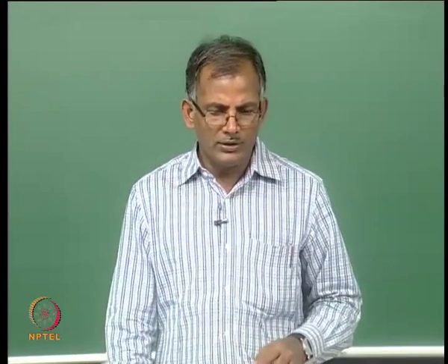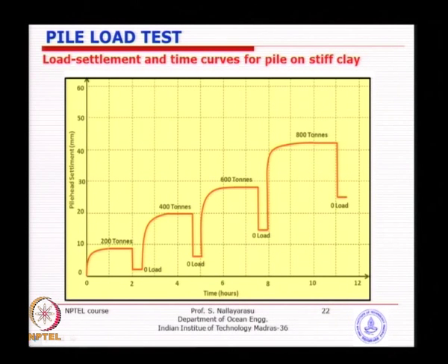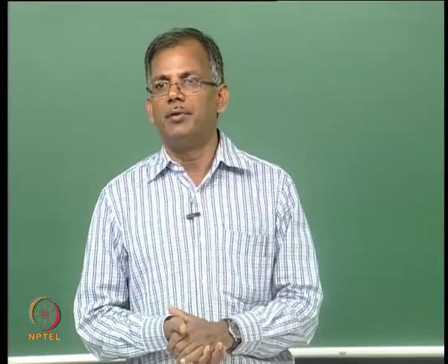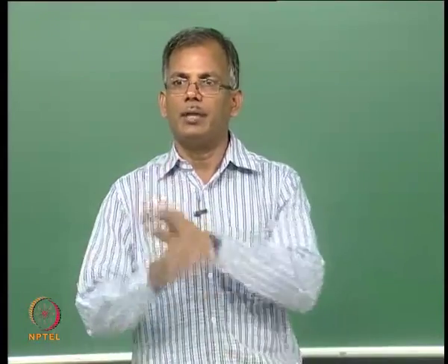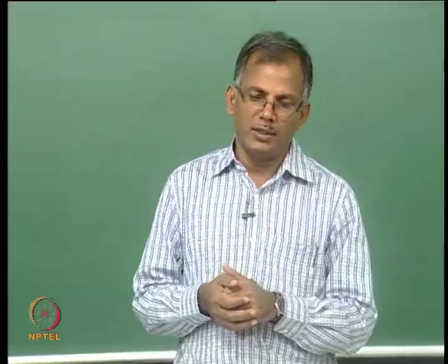So, the maintained load test is quite simple, and we will see the procedure later on, something like this. You see here you put the 200 tons and the displacement is increasing. When you do the unloading process, the elastic part will come back. If there is permanent deformation of the soil, that will not come back; it will be residual, so it will keep on stacking up. That is what we are interested in.